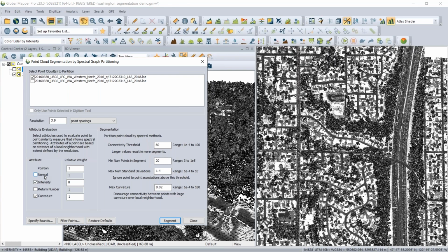So this is actually perpendicular to the surface. If you were to grid the point cloud data and then think about a particular location, what direction would a perpendicular arrow be pointing? For very flat ground areas, that's going to be pointing straight up. If you're going around a tree or something like that, especially through dense vegetation, it might point in all sorts of different directions and have normals that aren't smooth and continuously varying. So we can use those statistics to help divide our data as well.